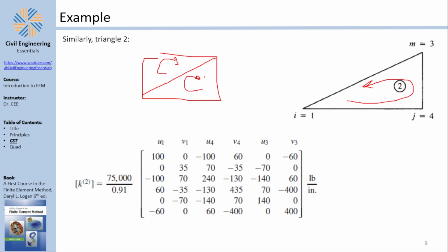You could go anything, but you have to maintain the same direction of rotation. If you choose the nodes to be in a clockwise manner, you have to use clockwise everywhere for the same plate element. If you choose counterclockwise, then you have to choose counterclockwise everywhere for the same plate element. And to just spare you the headache, I highly recommend that you use counterclockwise for defining the rotation of the element.